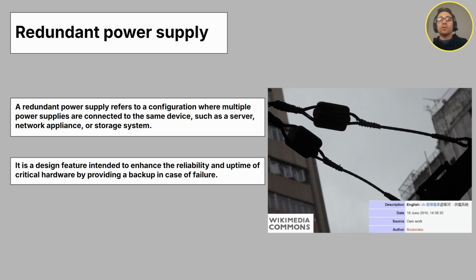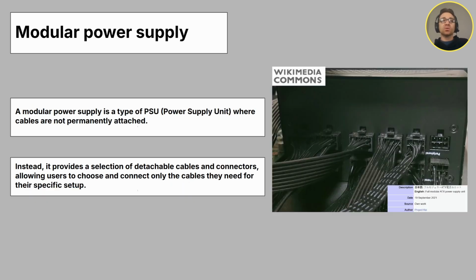Now, in relation to exactly how this works, you might be thinking, wait a second, we've got 2 power supplies plugged in. Isn't that going to be double the power? No, not exactly. If both are plugged in and both are functioning well, what essentially happens is they share that load 50-50. So you're still getting the same amount of power coming through as you would if only one were plugged in, but they're just splitting it down the middle. The moment one disconnects, generally that is detected by the other one, and that then shoots up to supplying 100% of the power. Okay, so you're not going to overload your system with a well-designed redundant power supply. That's important to know, and just keep in mind that's roughly how it works. Okay, so that is what a redundant power supply is.